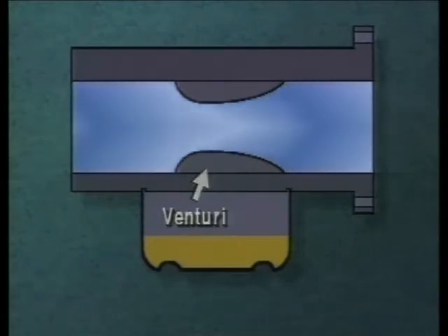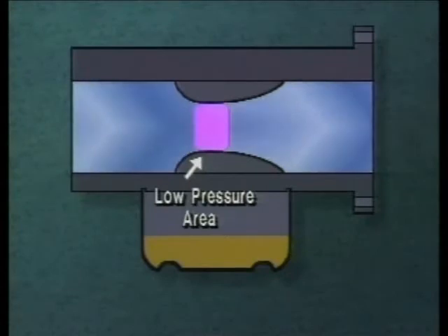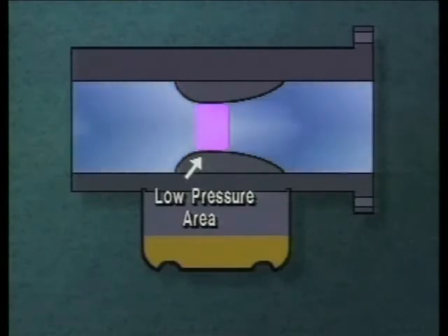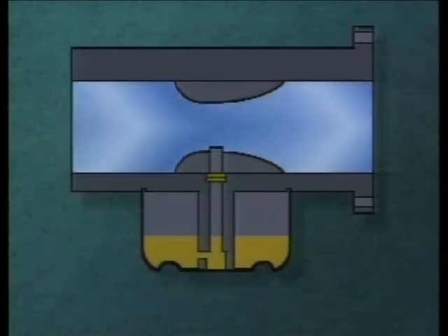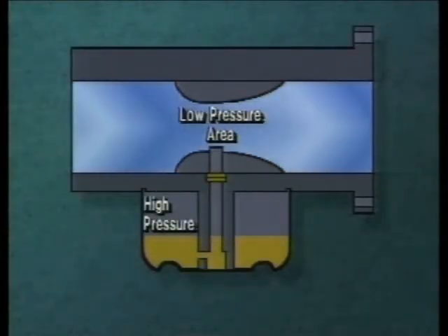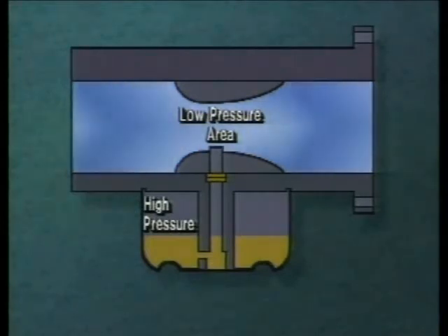The air must increase its speed in order to maintain the same volume of air passing through the venturi. The result of this increased airspeed is an area of low pressure within the venturi. This pressure difference between atmospheric pressure and the lower pressure in the venturi can be used to push fuel. We know that if we put some gasoline between the high and low pressure areas, the higher pressure will push the gasoline toward the lower pressure, through the tube, and into the airstream.